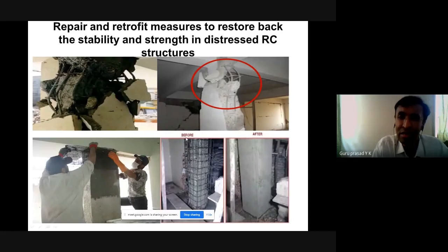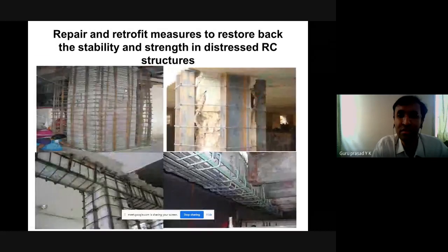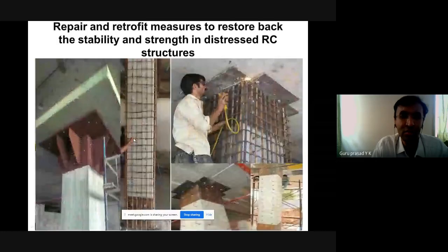For that, I design the retrofit, and I put this reinforced concrete mesh, this reinforced concrete cage, and I concrete it outside this mesh using micro concrete. Usually self-compacting concrete is used for the retrofit. So here also you would see, this is the damaged part where damage assessment using NDT is done and later the retrofitting is applied.